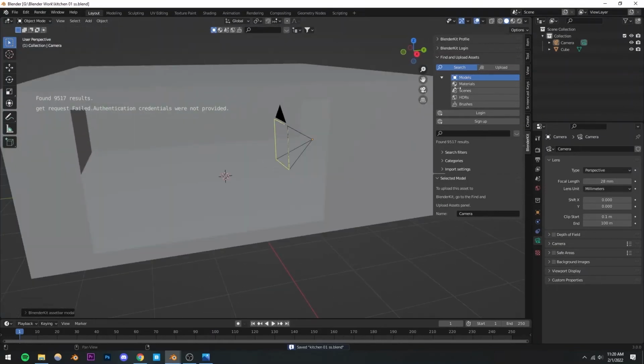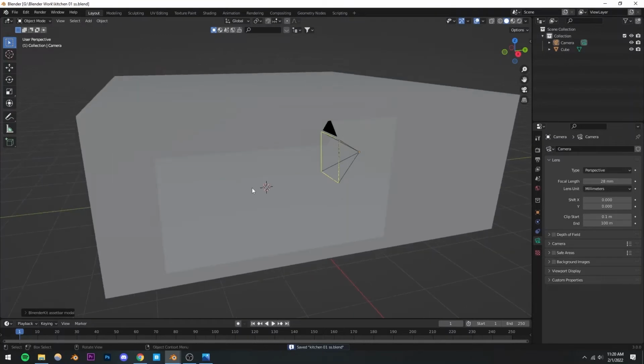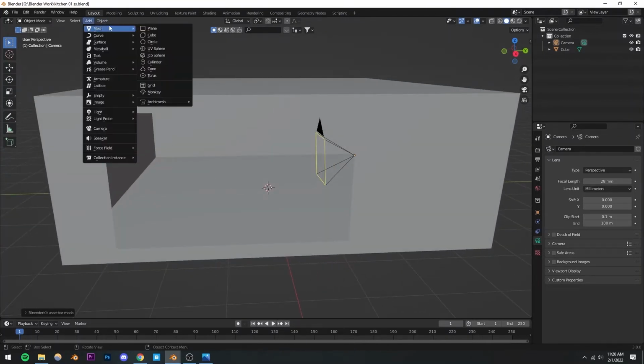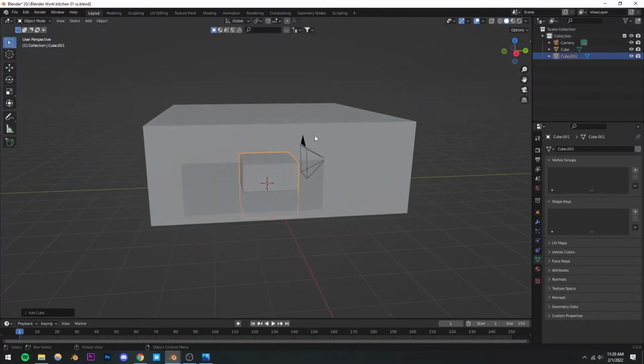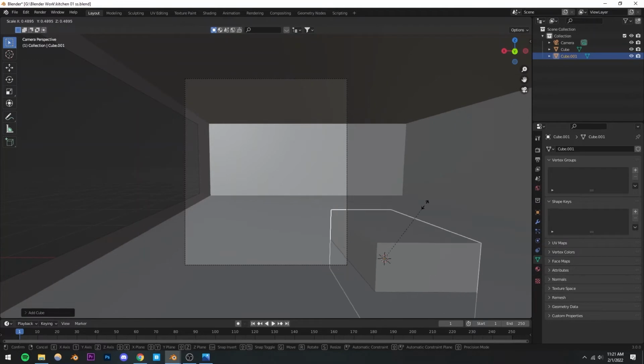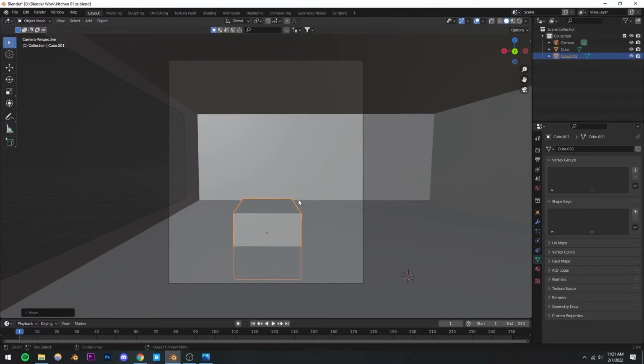One thing I'm going to do before we start using BlenderKit is create the countertop, which is very easy to create, so I'm just going to make that on my own. I'm going to create a cube. Let's go to our camera mode, and I'm going to scale it down, of course. I'm going to press G and Shift Z so that I'm not moving in the Z axis, only in the X and Y axis. I'm going to place it something like that, maybe.